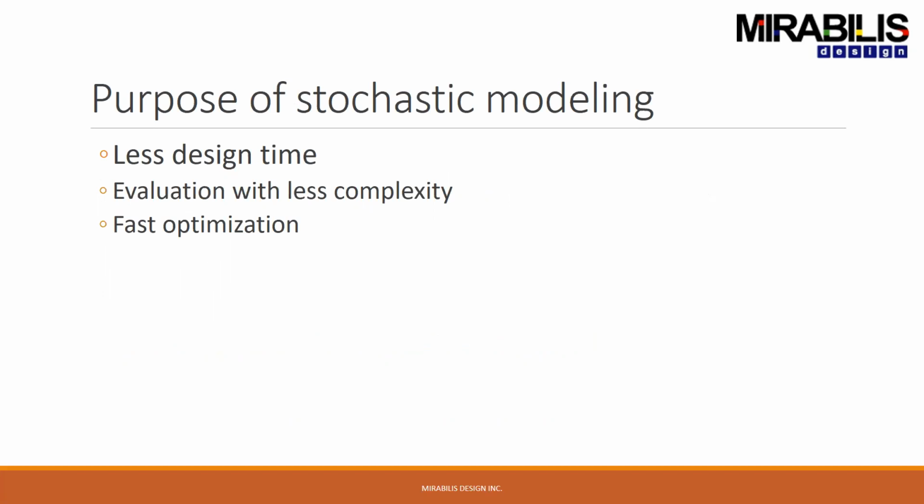Everyone knows the cycle-accurate design is more precise in the evaluation, but choosing this approach for all the cases is not efficient. We have to use cycle-accurate modeling to verify the functional correctness of the system, but for other aspects like power analysis and performance evaluation, it will cost more design time and testing time. Designers can choose this cycle-accurate model for these purposes, but it is better to choose the stochastic modeling for faster simulation with lesser overhead.